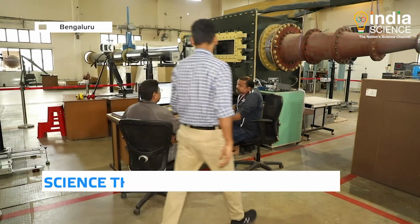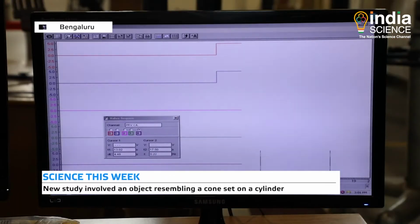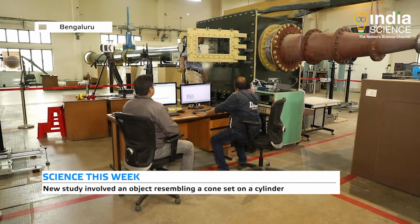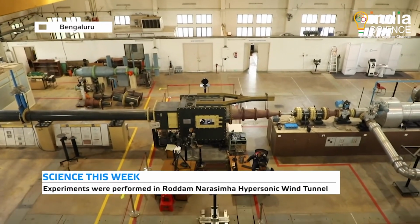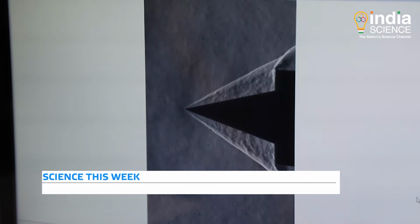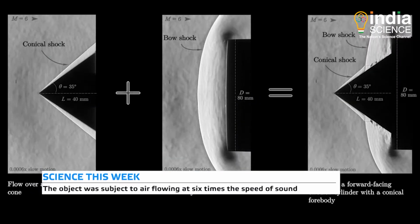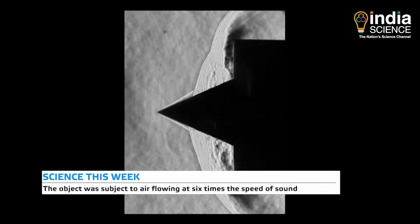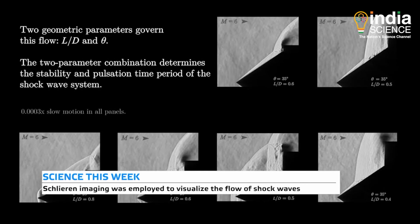The researchers experimented with a simple object resembling a right circular cone set on a cylinder. The experiments were performed in the Roddam Narasimha hypersonic wind tunnel, where the object was subject to air flowing at 6 times the speed of sound. That is, Mach number 6. To visualize the flow of shock waves, Schlieren imaging was employed using a laser and a high-speed camera.